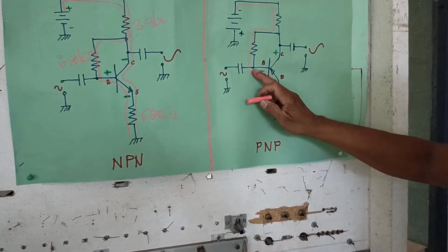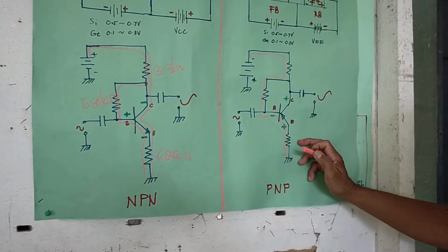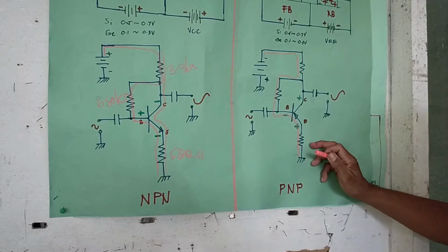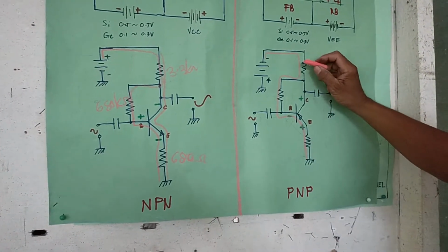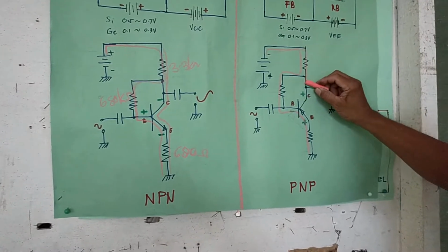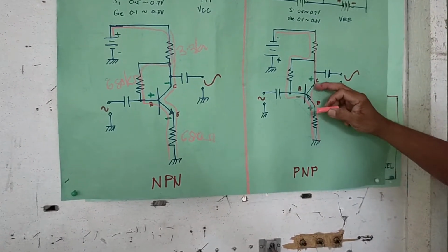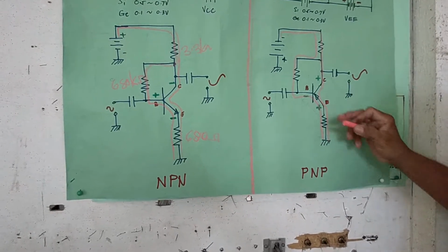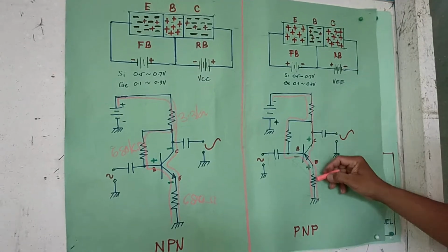So there is base emitter current. The voltage again here is 0.5 to 0.7 volts for silicon. Then, if there is emitter base current, there is also collector emitter current. The resistance of this junction here, emitter collector, is lower. That's why there is an amount of current flowing here.